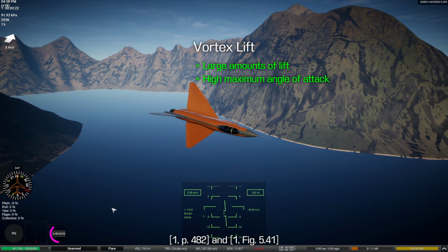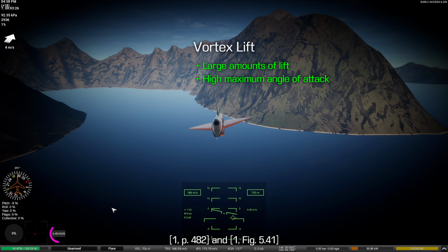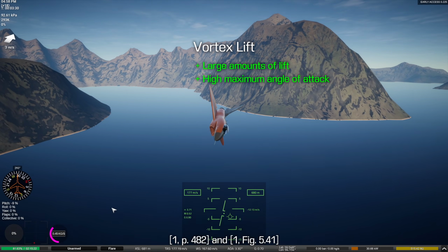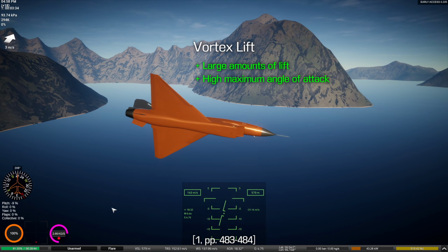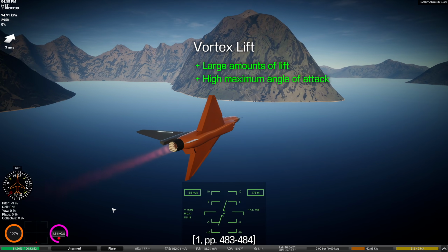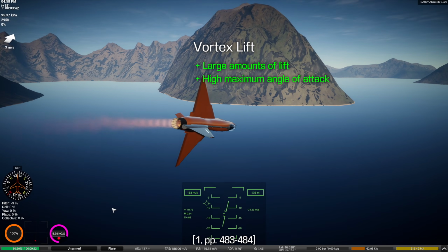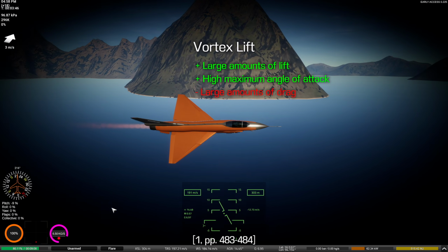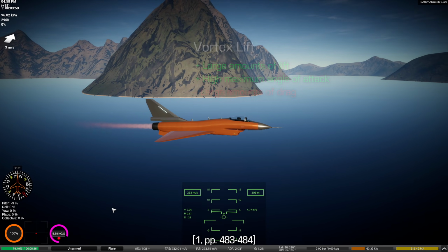One drawback delta wings face is that their lift curves are quite shallow compared to more conventional wings, although this should be no surprise considering their typically low aspect ratio. The drawback of vortex lift is that although significant lift is generated by these vortices, at higher angles of attack the normal force the surface experiences is tilted aft, causing significant drag. As a result, lift-to-drag ratios of delta wings at lower airspeeds are often poor.